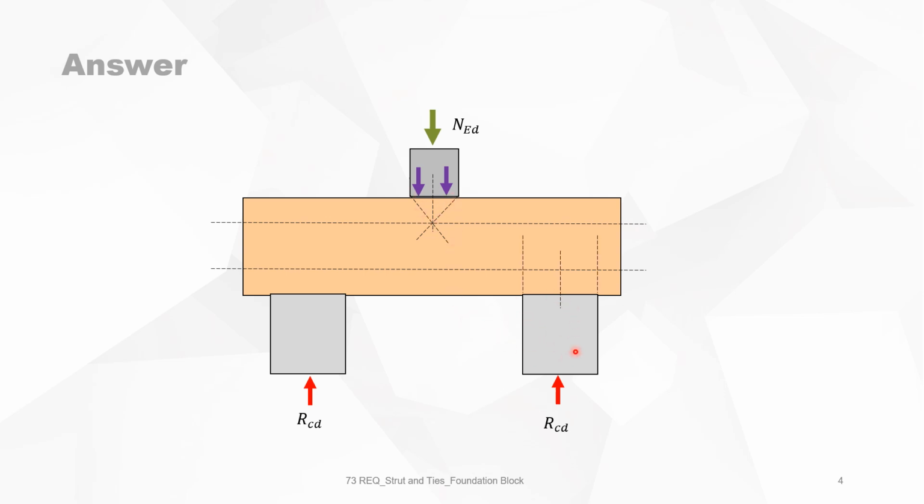We do the similar thing for where the piles are closing into the foundation block, and this is also the knot at the position of the pile. And when we connect those two lines, you see that we have now the two inclined compression struts.